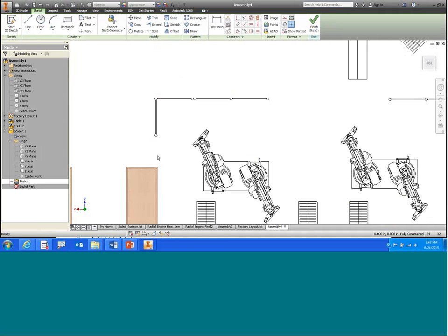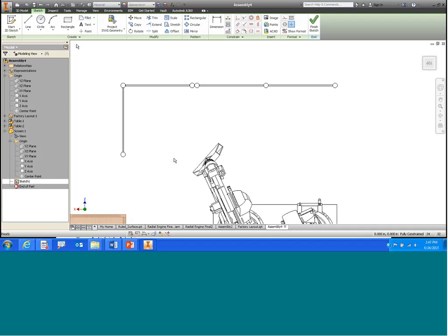Okay, there we go. And what I want to do now is use that geometry from that associative underlay. So this new command that is what you use to project is called Project DWG Geometry. So you can see it's brand new in the sketch dropdown. I can select this, and this little ribbon mini toolbar opens, and I can select my entities.